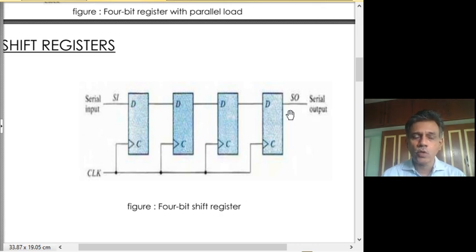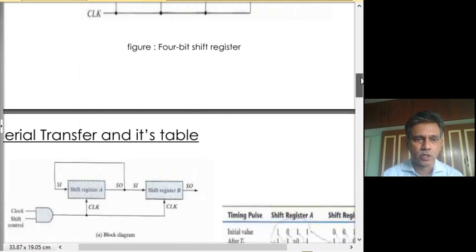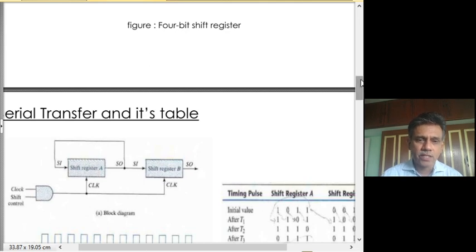Now 4 such units connected in this manner will constitute a 4-bit shift register. Now again we will encapsulate it into a circuitry and use that building block as a 4-bit shift register, and that is what is being shown here. So in digital circuitry, this kind of hierarchical encapsulation of circuitry will quite often be used.